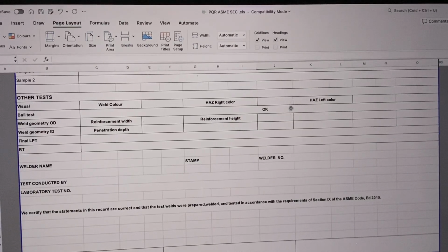Then the reinforcement weld geometry, penetration side: what was the depth after flushing, after grinding on the reinforcement side? Did you keep anything 0.2, 0.3 millimeter extra, and was it machined later on when the specimen was made? Was the specimen completely flat, or does the code allow you to keep some reinforcement on the weld, and then you tested it? So what was the cross section of the thickness you took for the calculation of area, because your strengths are going to be force divided by area.